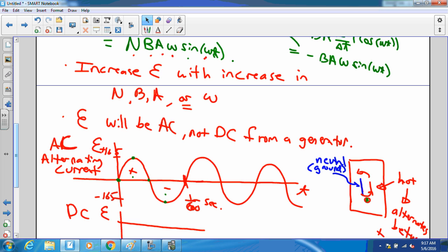So the bottom line is that if, for whatever reason, the power station ground were to not be at zero relative to the stuff in your house, then you could actually get significantly shocked. So this actually ties into the ground in your house. In other words, the pieces of metal, some large piece of metal in your house, to ensure that 120 will be 120 and not something much larger.